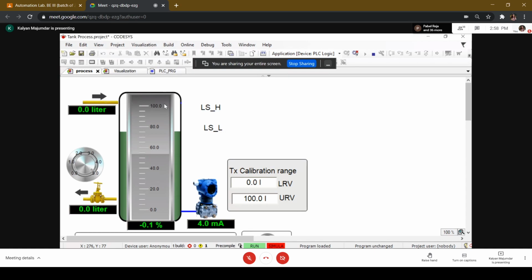So the inflow into the tank would have different values. One is the normal value if the whole system is operating fine, if the pump is operational. It is 0 if the pump is off. It is 0 if an overload condition occurs. And it is some value between 0 and the maximum value if there is a fault condition, implying leakage in the pipeline, some kind of blocked filter, some kind of blocked valve, or whatever.